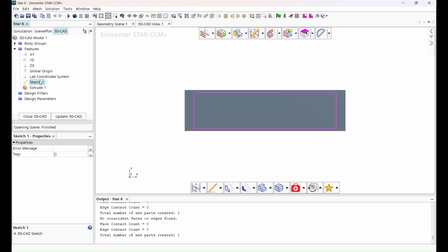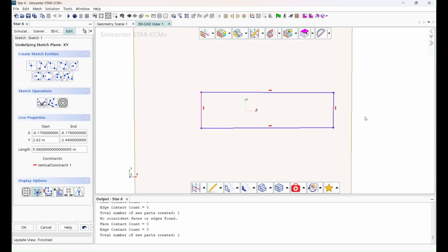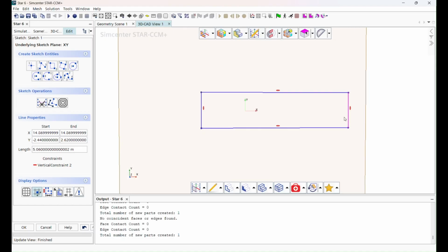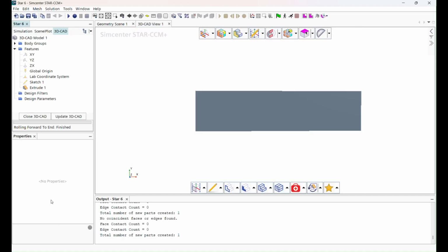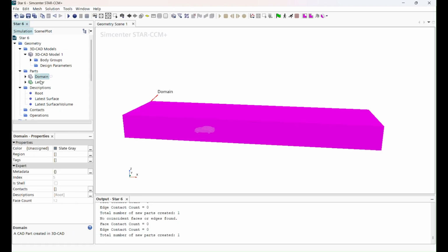I'm then updating the CAD so that the changes are seen on the geometry and that the part is changed as well as the 3D model. You can keep going back and reiterating, but as I mentioned, if you are working with a real-time wind tunnel and you have actual measurements, make sure you use this so that it is very accurate to what you will be seeing in your specific wind tunnel scenario in real life.